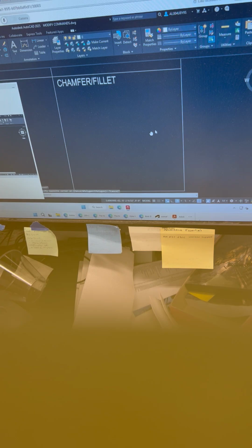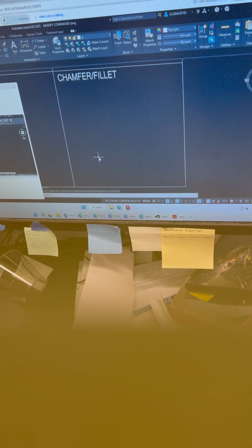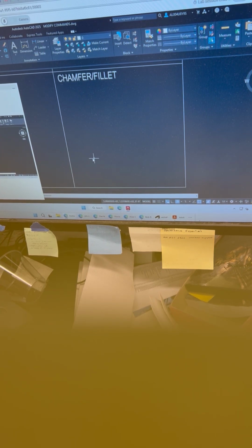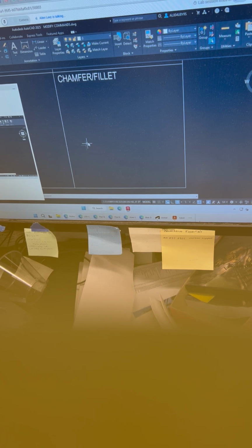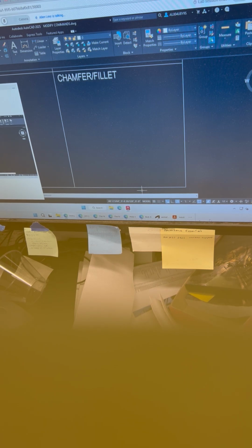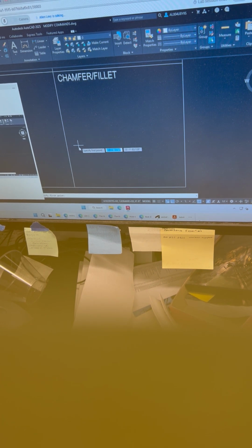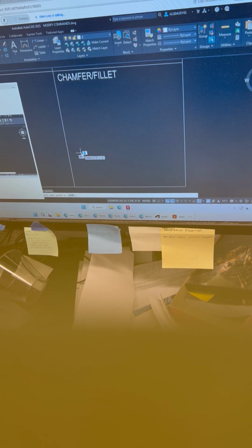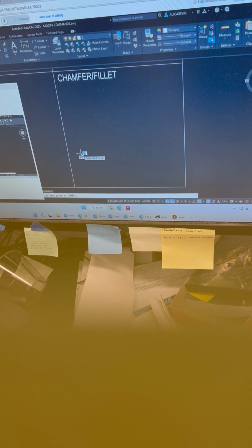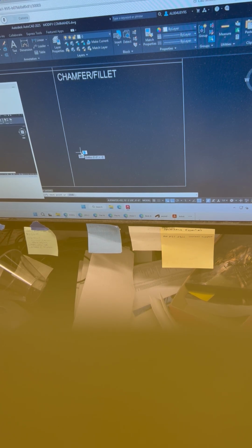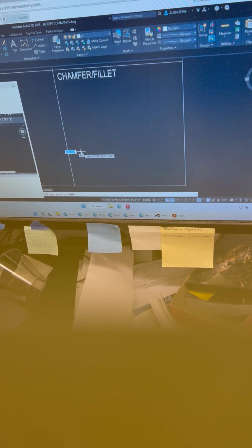And then what I want you to do is copy this line, and I need it to be copied along the same trajectory. So I don't want you to go off at an angle. Copy it over approximately, doesn't have to be exact, approximately 4 feet. And it has to be exactly in the 0 degree direction. I want the two lines to line up, in the same alignment. So I'm going to just move it over maybe 4 feet.